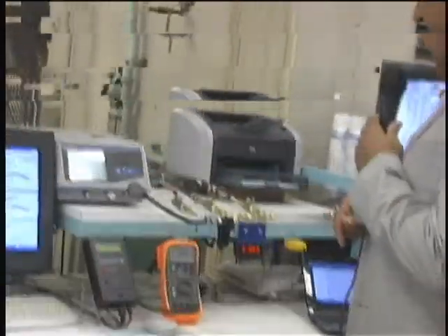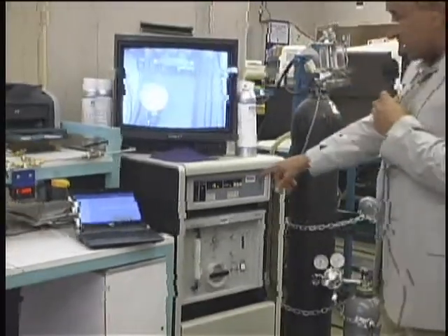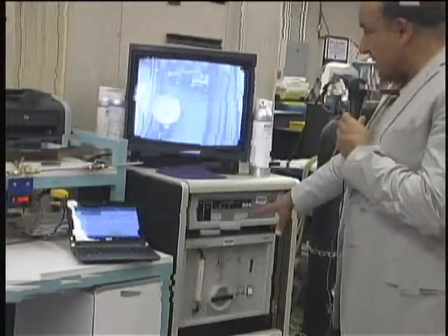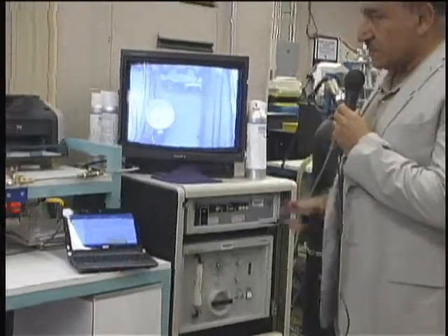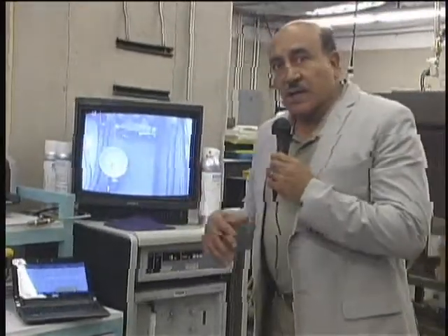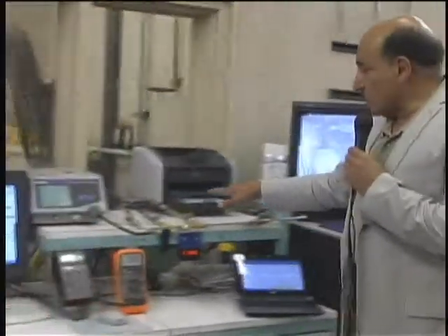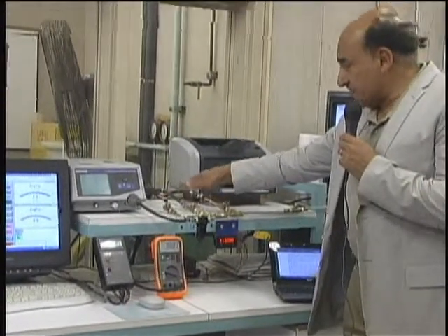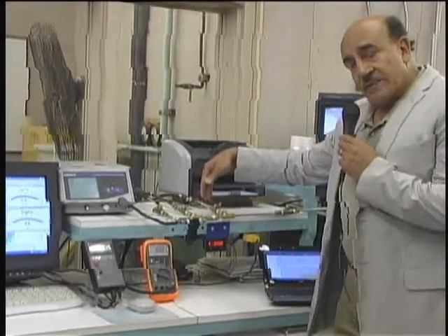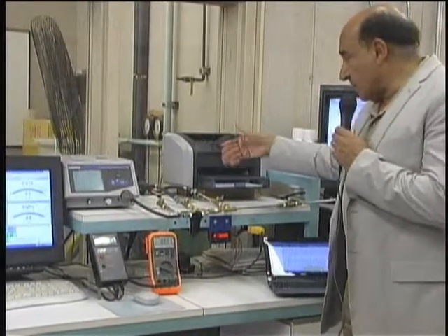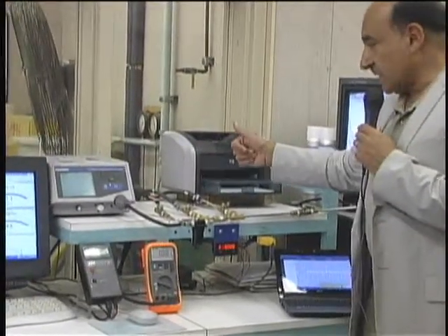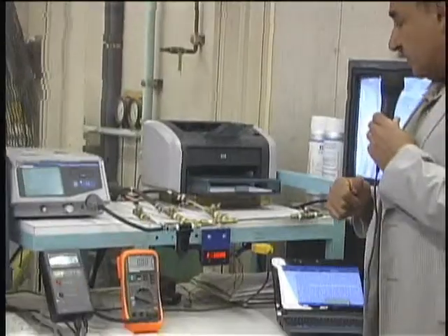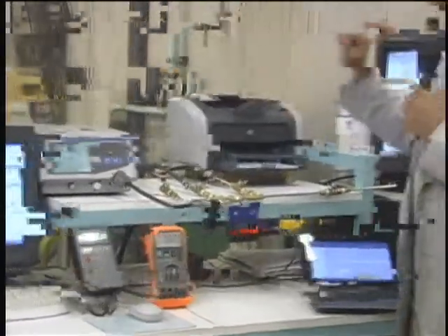You also have a sampling unit that gives you analysis for the NOx itself. So between these, you'll be able to determine the composition pre and post the catalytic converter. To control the sample, you can draw a sample of exhaust before or after the catalytic converter, and you also have the ability to purge that. The information can be printed here.